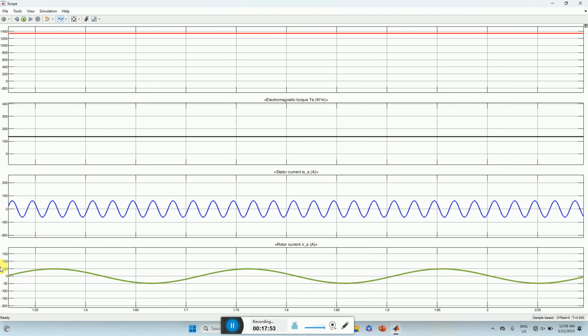Okay, these 3 cycles, let us say we are at 1.7 something, and this is reaching here at 1.9, so 0.2. You can see that the rotor frequency has decreased, time has increased, and the stator frequency is 50 Hertz. So that's a reflection of it.